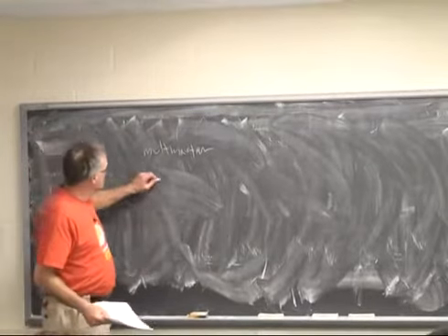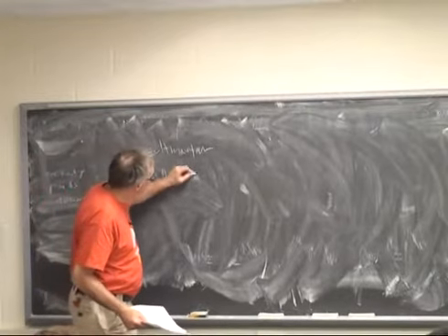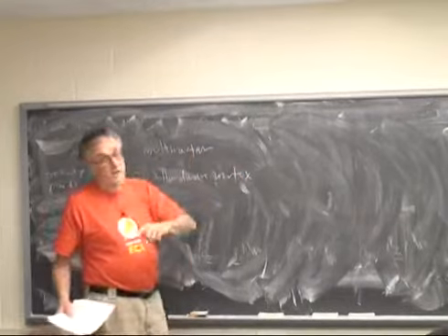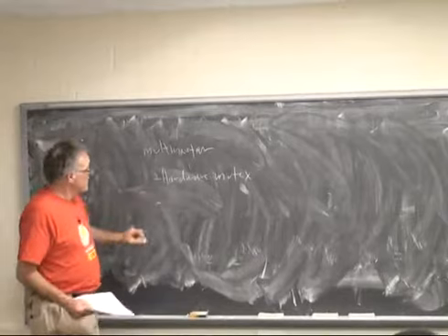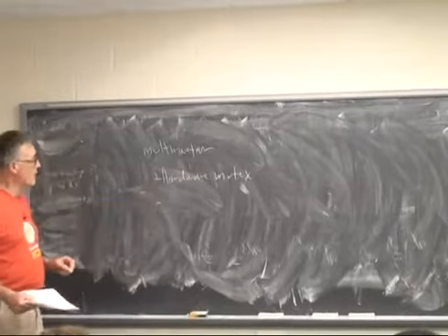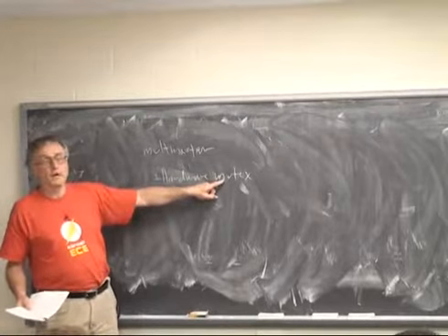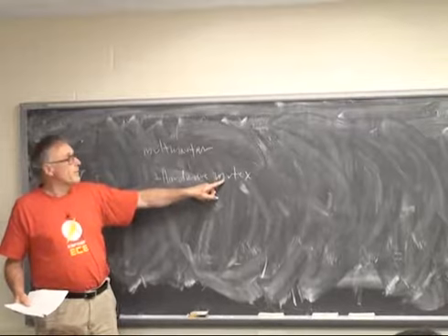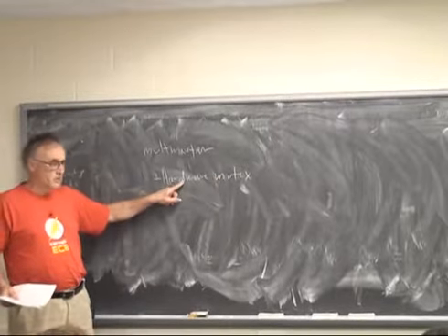One is a hardware mutex. This is not a software construct, and it has nothing to do with a multitasking operating system. It's a strictly hardware mutual exclusion operator, so that in one atomic operation, a CPU can say, I want a resource.